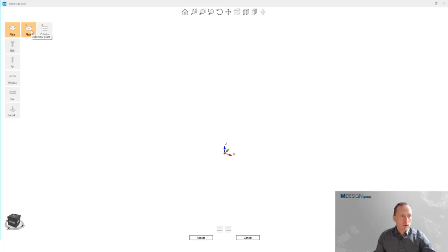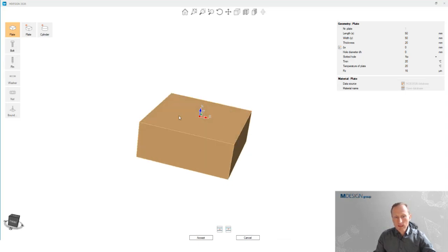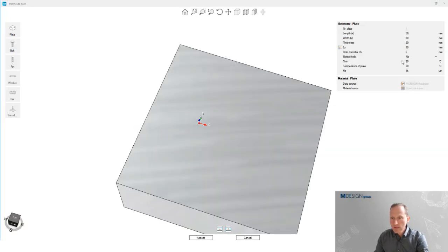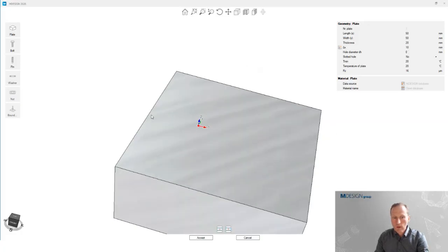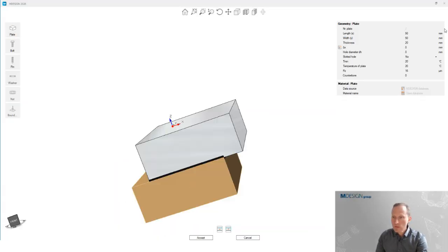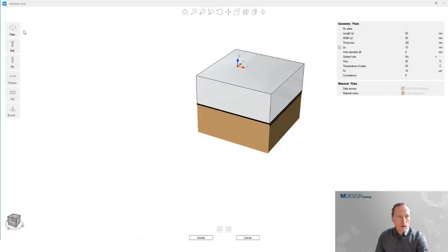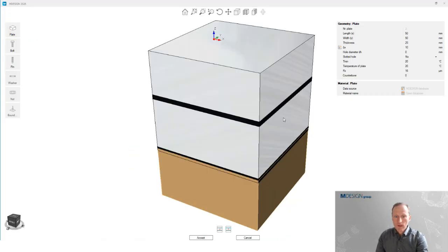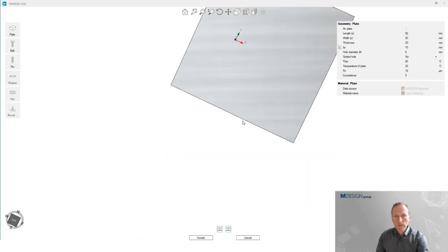So for example, you can use round and rectangular plates. If you want to create a small distance of the bolt to one border and cut the pressure cone, then you must use these rectangular plates, because with this value you can say this is closer to the outside border than the other side. So maybe I choose 3 plates,